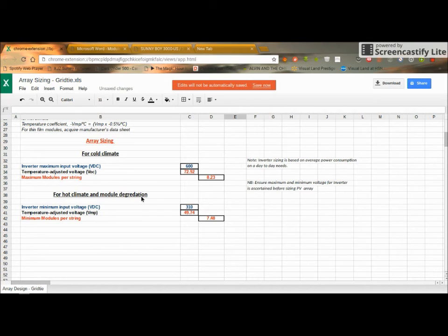So some of the photons may leave over the years, and so the entire string, as the years go on, may reduce. So what do you do? You factor in for that years of service, that degradation, so that by 25 years, your power output would not have dropped significantly. And so in our template here, we have input that module degradation in our calculation.